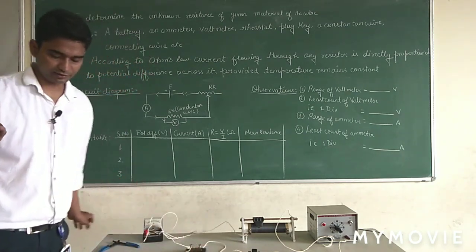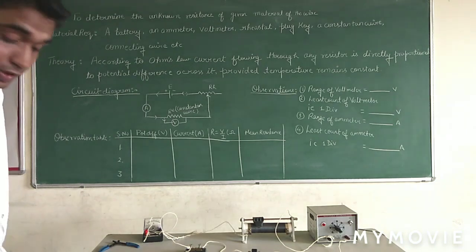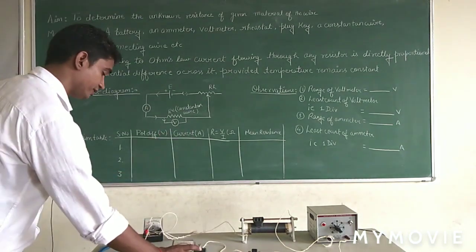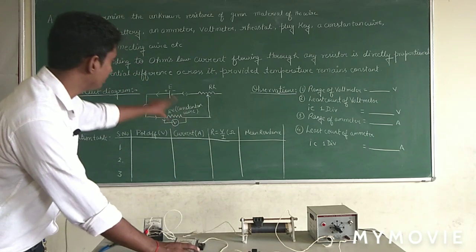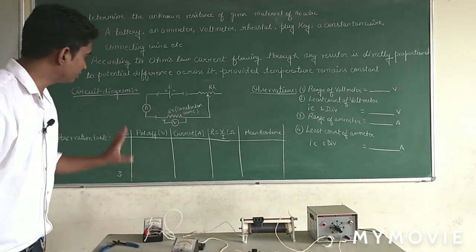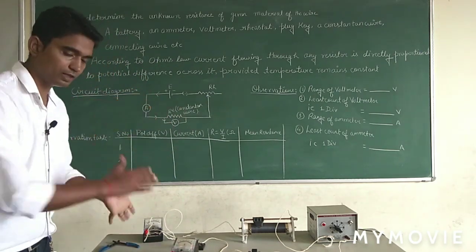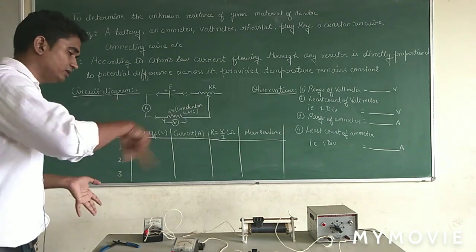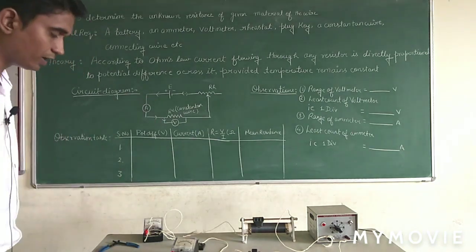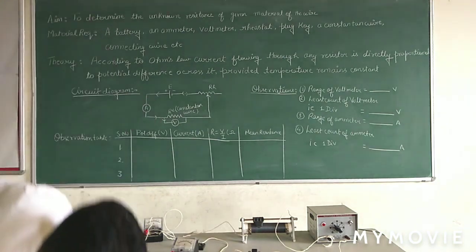The one device that will provide us the potential difference is our voltmeter. So all the elements are connected in series, except the voltmeter. I have kept the voltmeter aside and connected all the circuit elements in series. Now I would require two pieces of wire.